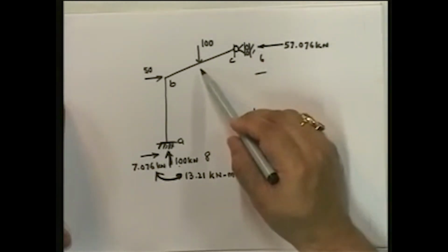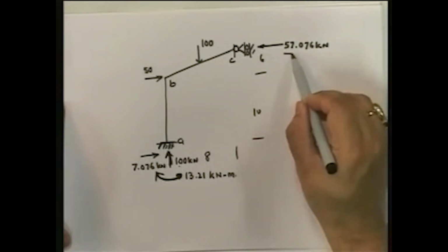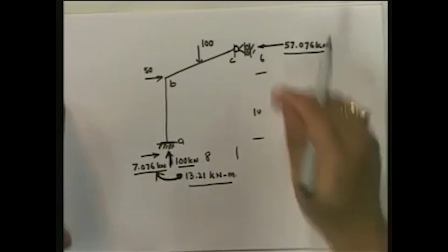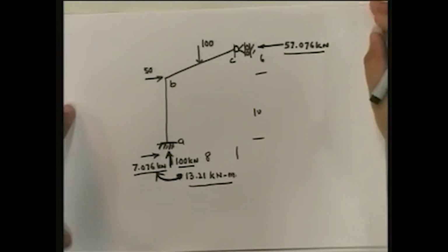Till now, the structure is more flexible, the support reactions are less. In other words, if serviceability is not a criterion, making the structure more flexible by removing a restraint of support seems to make the structure much better. However, let's look at the bending moment diagram.